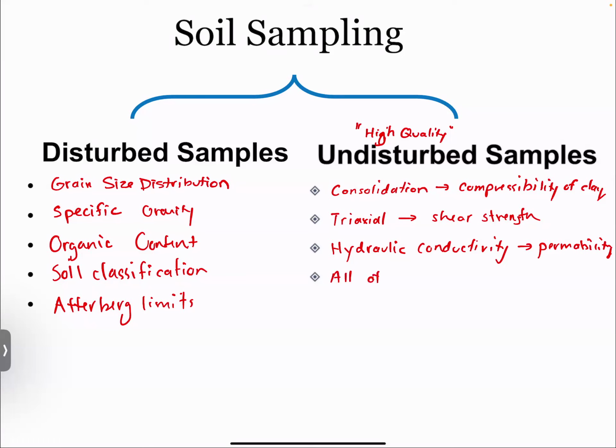So for all other strength tests, we usually need what we call in situ conditions, or what the soil is actually like under the ground. If we were to use a pressure washer to bring up the soil, we are remolding it, it's in a completely different state. So we can't test it in the lab and say that that testing condition is equivalent to what is actually underground.